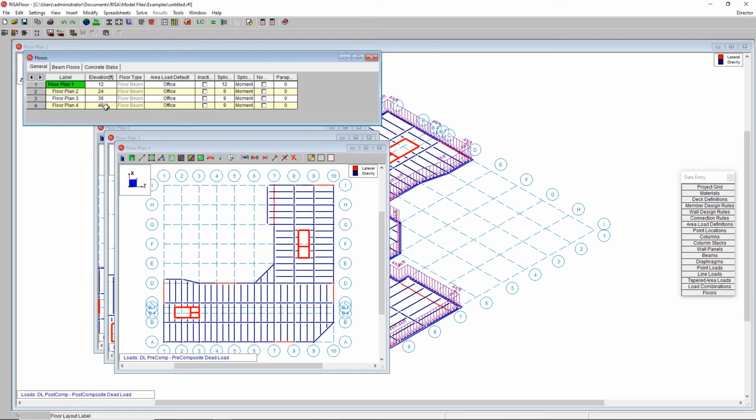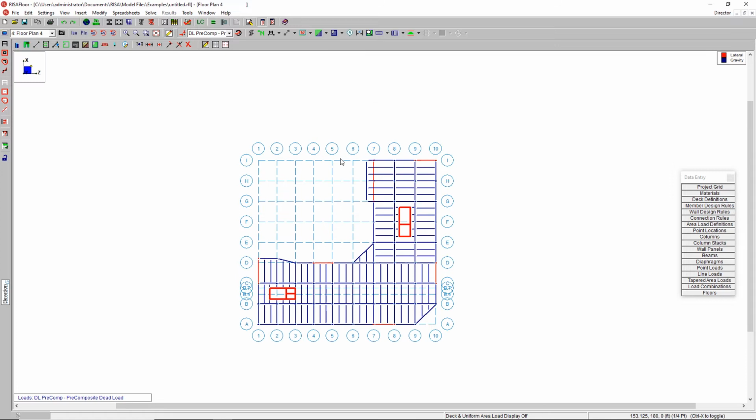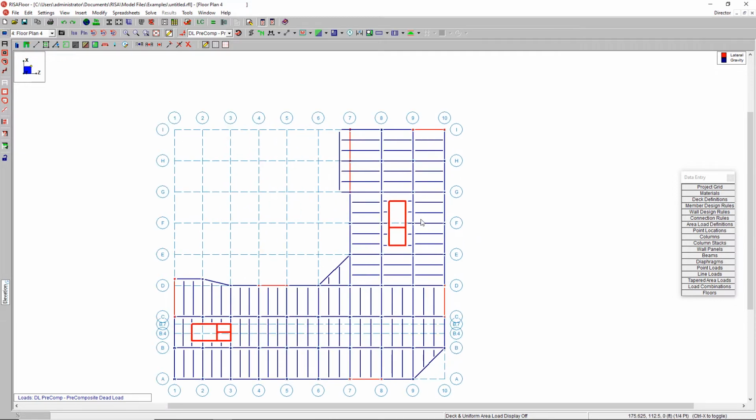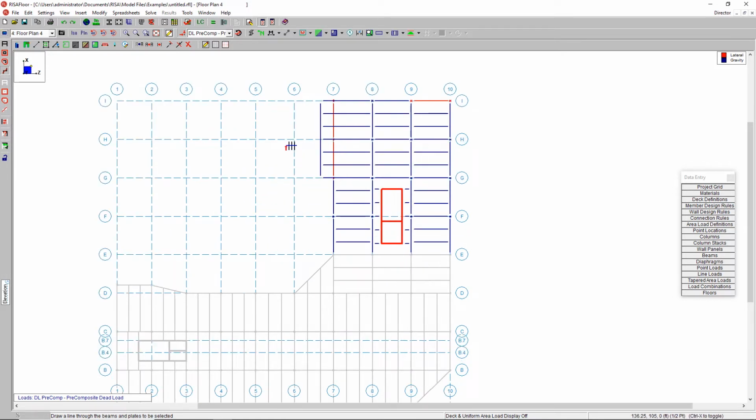Let's double check here. We've got 48 feet all the way up the structure, and now at this level, I'm going to start to remove some of the sections I have there. So this whole area is going to be starting to trim back. The way I can do that is just by unselecting a large portion of the model and then selecting this using the group selection. And I'm going to pick up this whole area, and I'm going to basically remove a lot of this area here. So I can do this quickly by just saying delete.